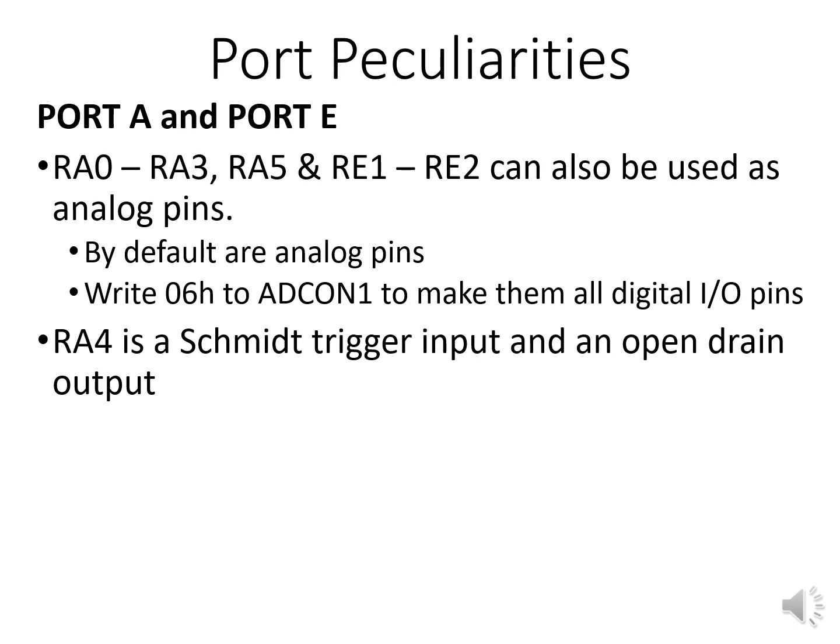Pins RA0 to RA3 and RA5 on port A, and all the pins on port E are also used as analog pins. By default, when we first switch on the PIC16F877, these pins are analog pins. You will need to configure them as digital I/O pins.